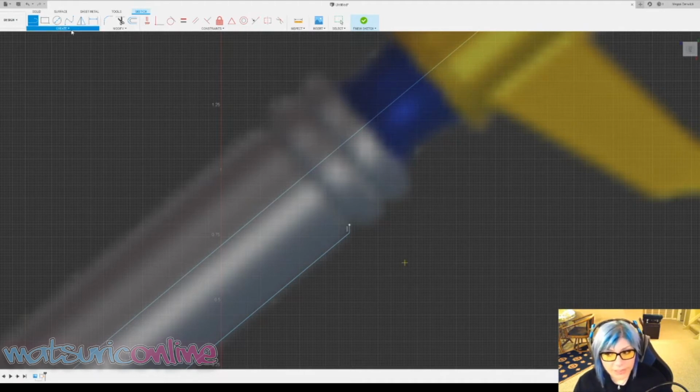I want to make an arc. So what I'm going to do is click this create button. Unfortunately, you can't see it. I'm going to go down to the arc function and go to a 3-point arc. I'm going to click right here, and then decide that I want my arc to go like this. I'm going to make one more. It's not exact, but honestly, I kind of like it.